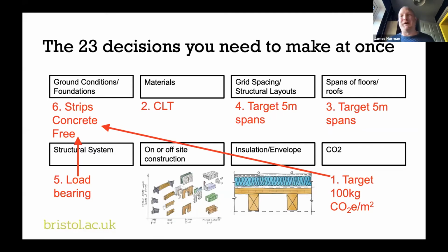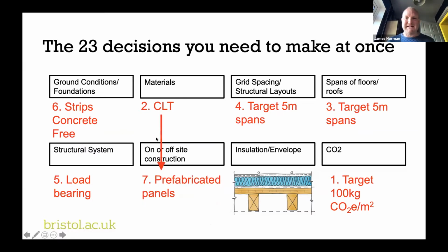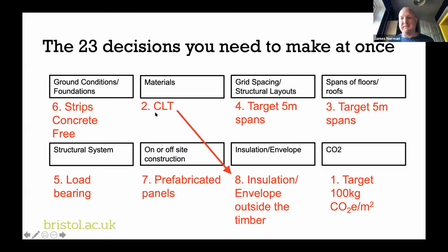And timber is light, so timber is reducing the load, and we're spreading the load. All of these things enable us to think creatively about the foundation type we have, and as I say, possibly go for concrete-free foundations. It also opens up the opportunity for prefabrication, which means a lot less waste, and we can optimize the usage of our material. And it means that we're probably going to design for the insulation envelope to be outside of the timber. So we're going to wrap the timber to try and keep the timber dry and warm, which is going to hopefully deal with its durability issues.